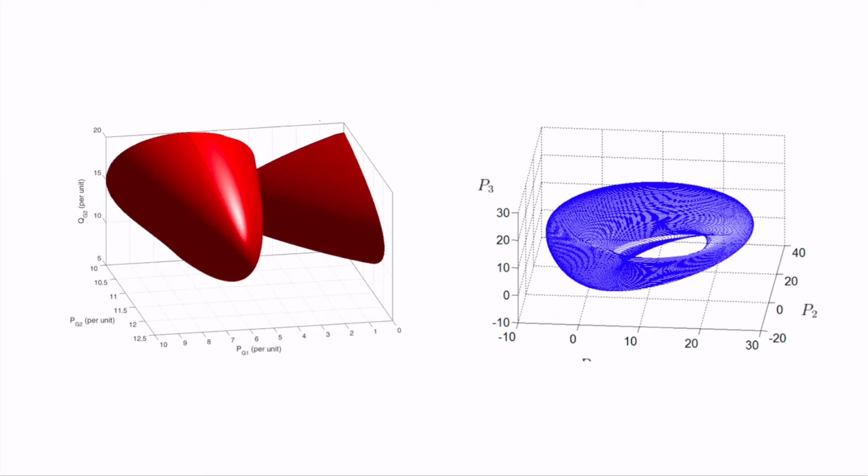On the left, you have a very simple case where you have only 3 elements: the active power generated by generator 2, and the reactive power of generator 2. So you have 3 elements that can vary in a very small system, and it looks like these very particular shapes. One observation is that this is non-convex because you already have 2 regions which are separate.